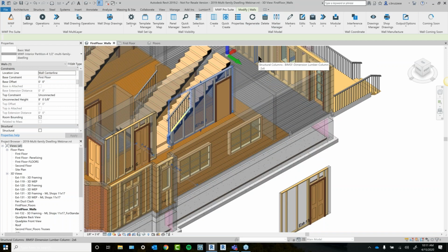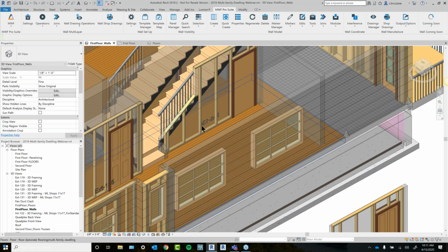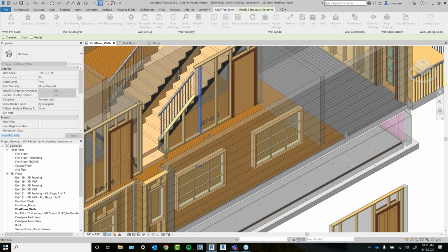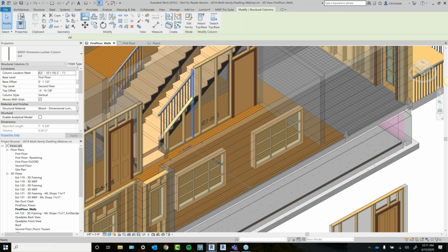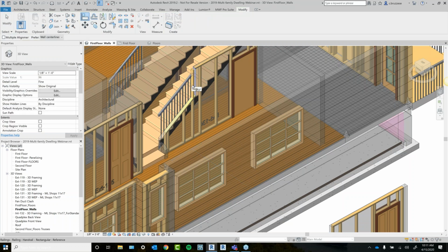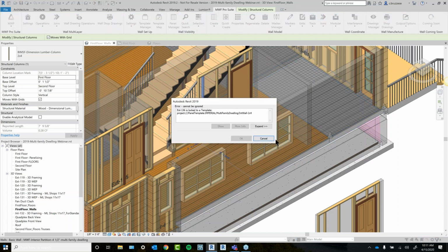Like I mentioned, it's a handy tool to have. I can still make manual edits to the wall with Revit if I need to, like copy and paste, maybe add an extra stud here to cap off my wall. You would have that option with lock to template as well. You can still make little manual changes, but the overall properties of that wall will stay locked.